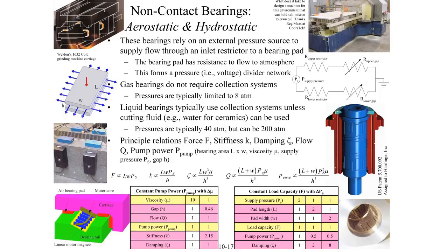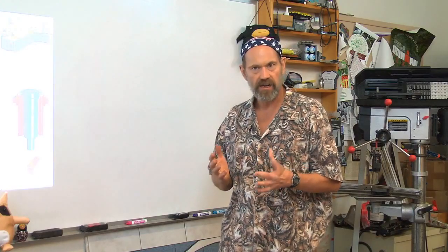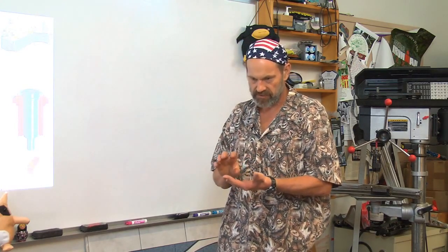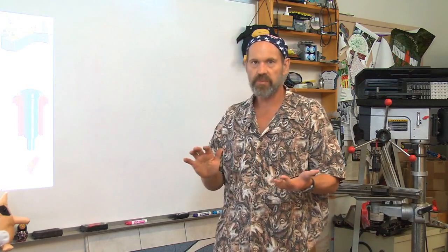Well, we just said that hydrodynamic bearings work very well because when you have a small deflection in the shaft, that's what enables the hydrodynamic wedge to build up in the first place so it can support a load. But what if I need a high degree of accuracy where I know that I must have the position of the shaft in a spindle to always be known and to be as stiff as possible.